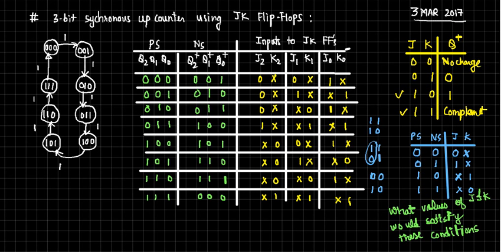Then now you should form... Now what was the next step? We used to express the inputs in the form of the present state, right? We are representing the inputs of the JK flip flop in form of the present state. So you form K maps. How many K maps will be required? 1 2 3 4 5 6 K maps, right? You see here the job is simplified.